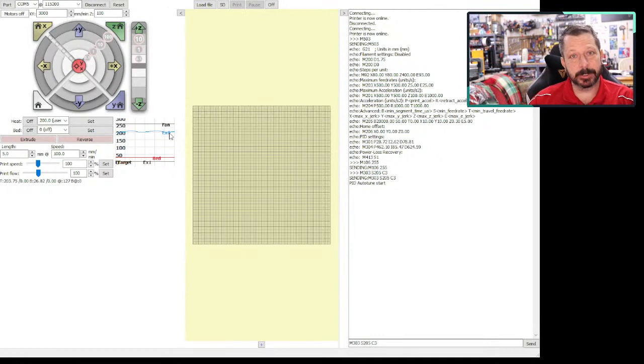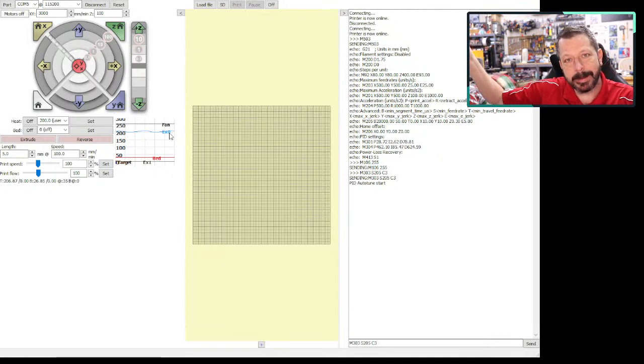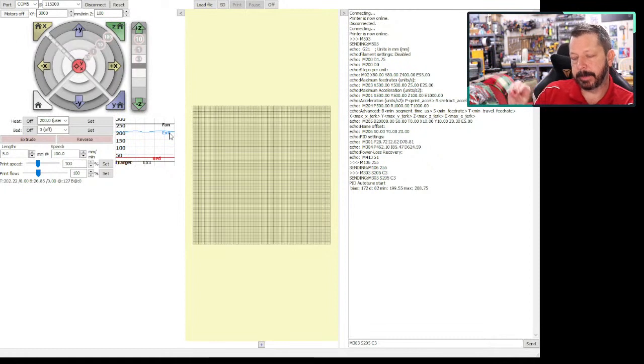The derivative is the slope of the line, so the rate that it's doing stuff. So if I know the slope and where I'm at and where I've been, then I can kind of predict the future. Because I know the rate I'm moving at right now, I kind of have some history information. I've got how much gain I've applied through the proportional constant, and I've got the derivative now, and I can predict the future. So if I have past data, current data, and a future prediction, then I can have much more control over what I need to actually do.